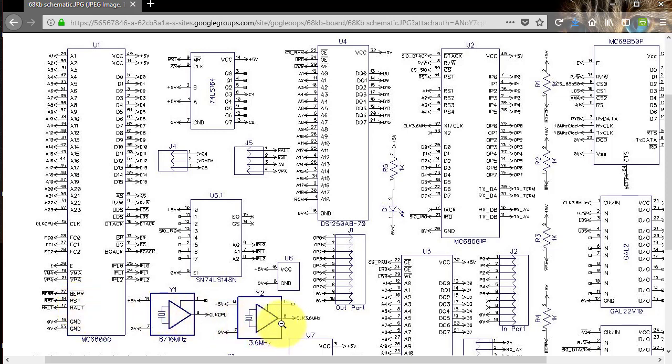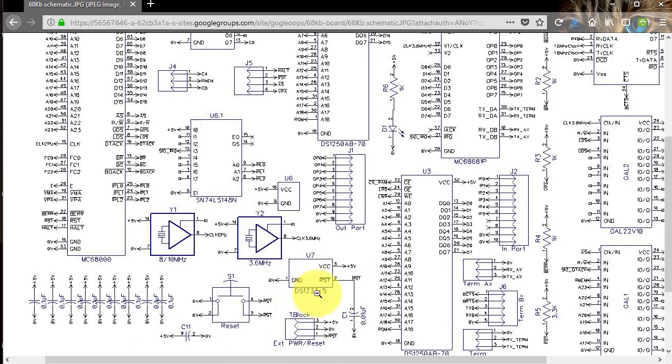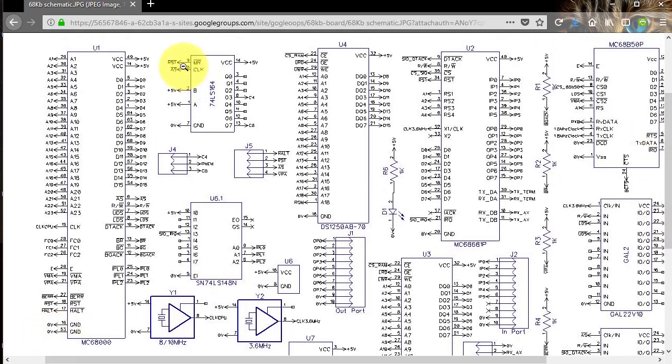They're usually driven by the reset circuit, which is part of the DS1233 IC, which basically gives a delay of hundreds of milliseconds on startup, and usually the reset and the halt lines are connected together. So you'll see on the board a set of 4 terminal pins marked H, R, A and V, and basically you connect the reset and halt lines together and AS and VPA lines together. Obviously the other pins, as you can see, are the ground and +5.